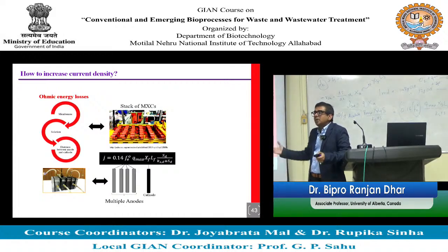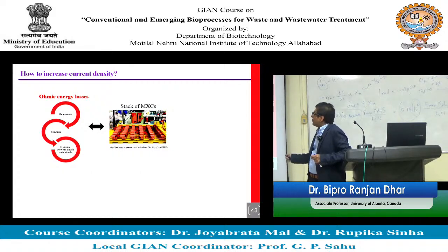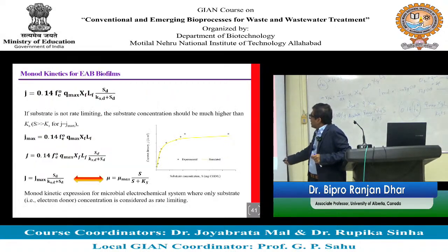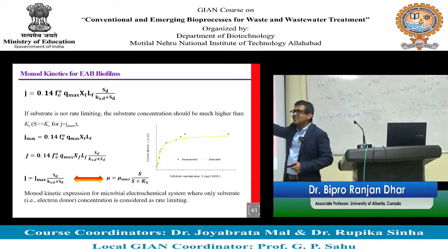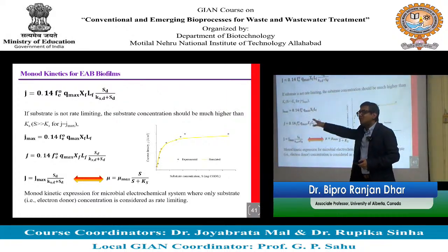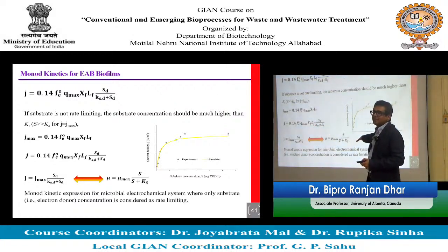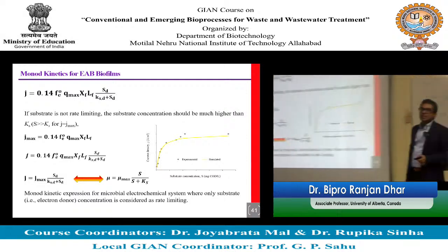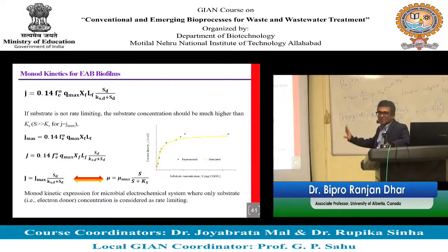So there could be a lot of extensions, but what we found is, if only one term can fit your experimental data, that means those other components or extensions may not be that critical, so they are not rate limiting. This one is rate limiting. This is the basis of all this, and this is actually the beauty of the Monod equation.